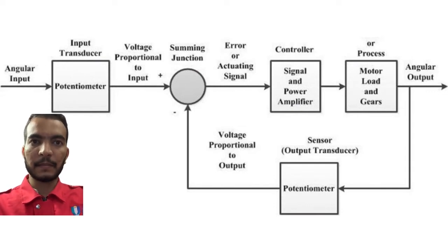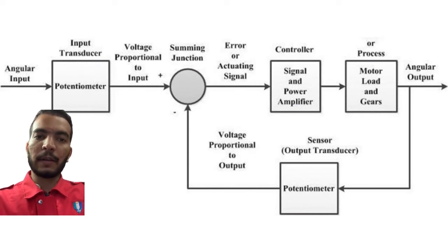As previously indicated, the potentiometer converts the input angular rotation into a voltage to start the operation. Similarly, the potentiometer in the output region converts the rotation angle to a voltage, which is given back to the input through feedback. As a result, the difference between input and output voltage is zero, so the motor receives no voltage and will not start as soon as the error becomes zero.